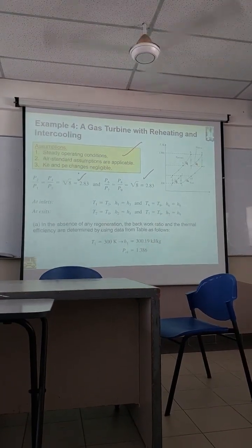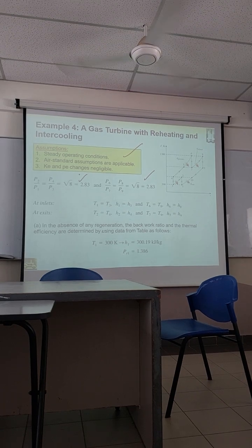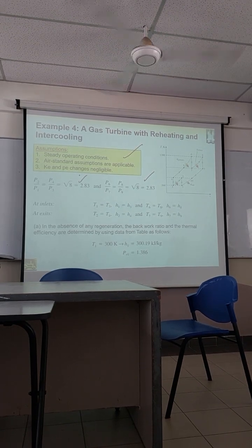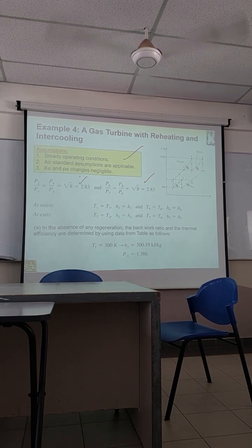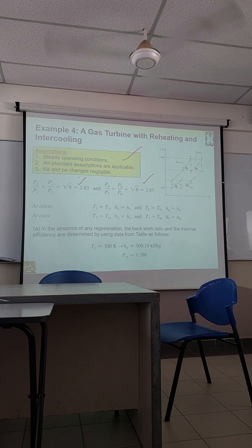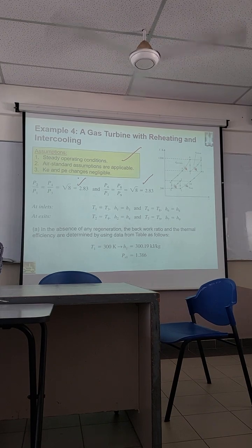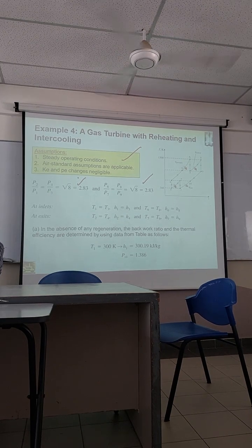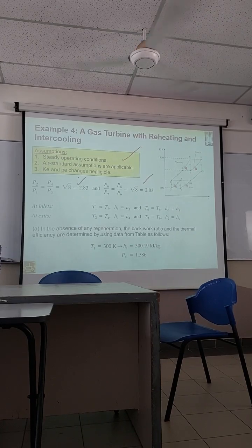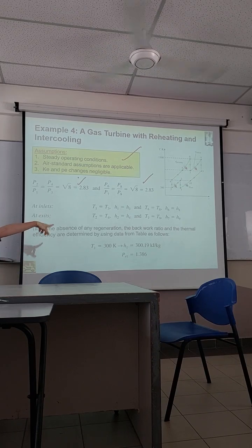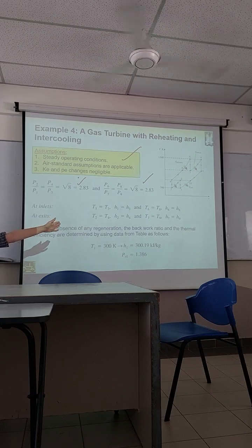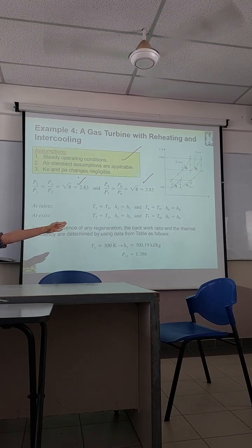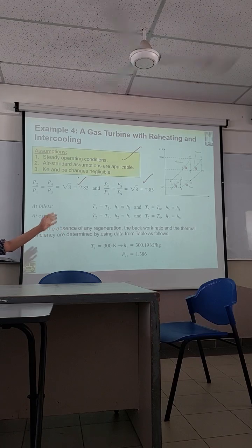Now, a very important part at the following part. You see, 4 and 2 are at the same temperature, right? 3 and 1 are at the same temperature. 6 and 8, same temperature. 7 and 9 also the same temperature. When you are dealing with an ideal gas, temperature is the only thing that matters inside the enthalpy. Which also means that T1 equals T3, H1 equals H3, and T2 equals T4, H2 equals H4, T6 equals T8, T7 equals T9, H6 equals H8, H7 equals H9.